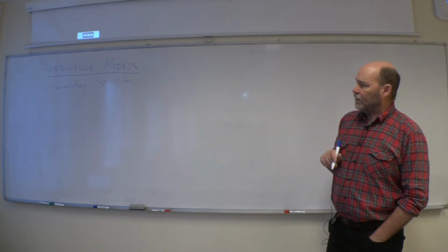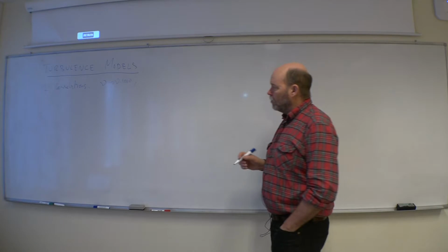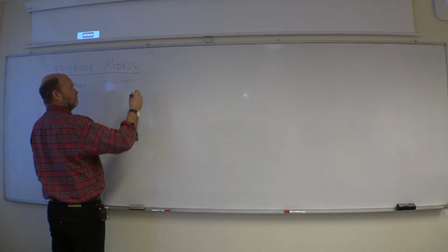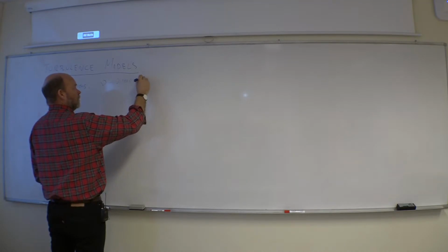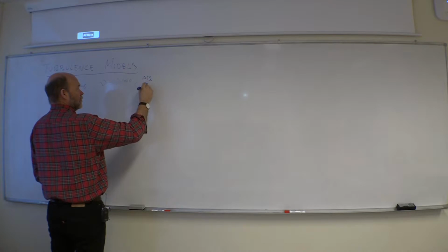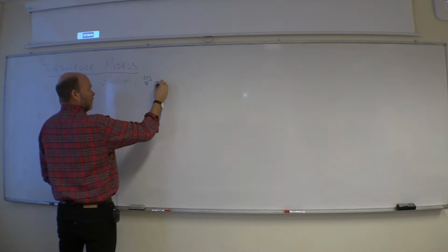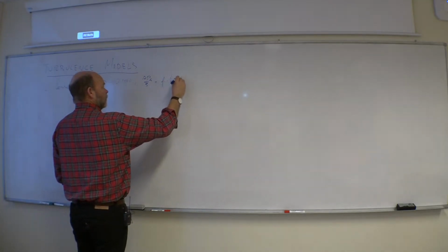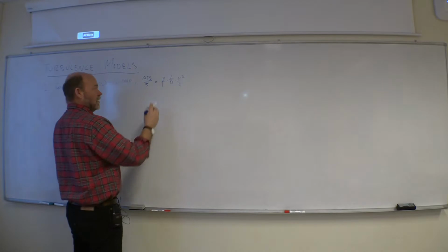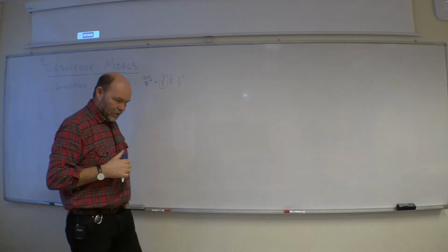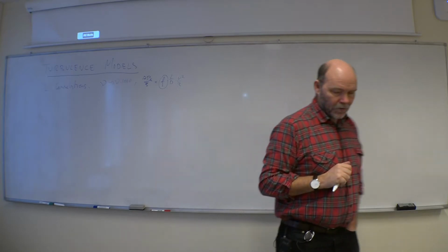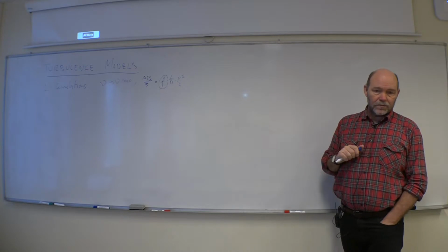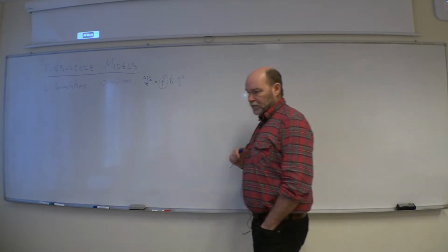More engineering for correlations. You have Bernoulli with losses. So what do you have in Bernoulli? You have a delta P loss over density. There you'll have a function, friction factor f, length over diameter, V square half, and so on. And this friction factor then can be found from a Moody diagram or simple correlations like Blasius, Prandtl.